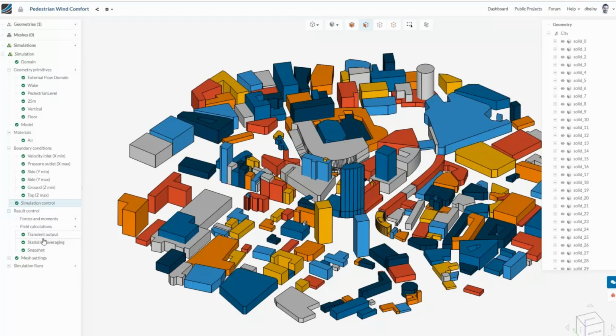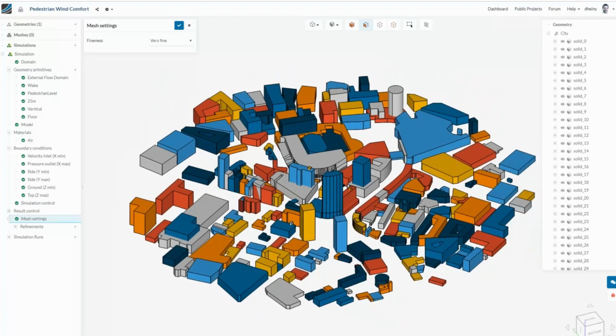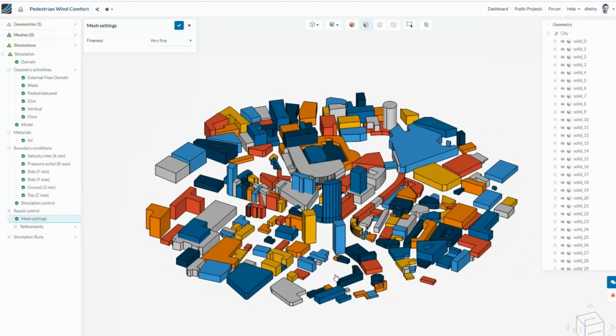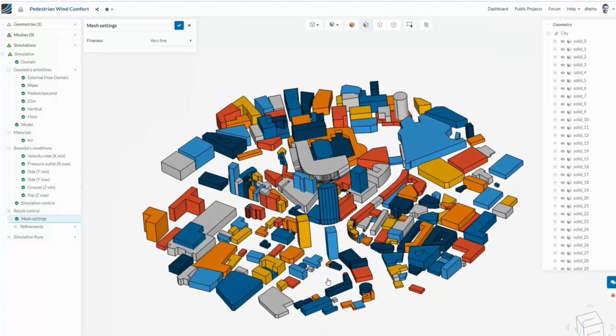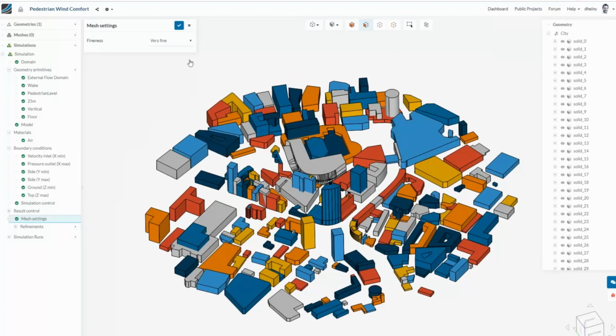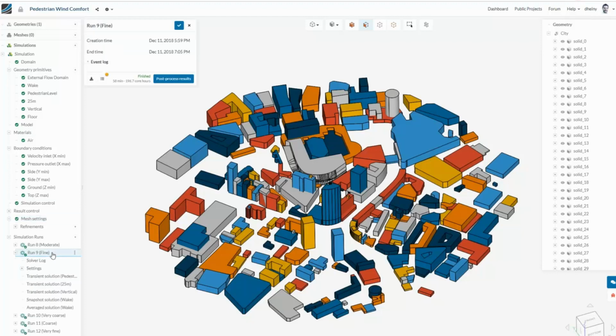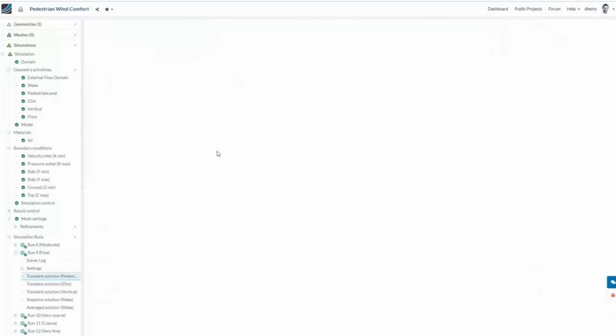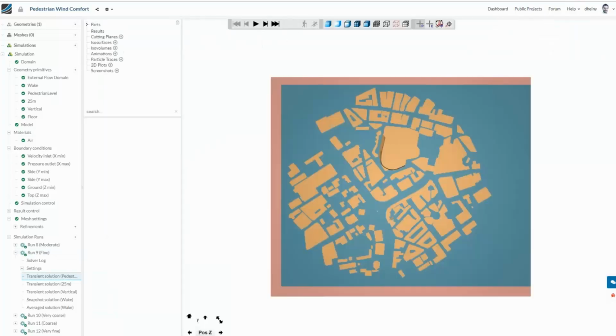Furthermore, anything else? The rest is maybe a bit very detailed. Then I can steer the lattice resolution. So again, we won't go into the details here, but I can drive the resolution of the mesh depending on which areas are of interest, which are not. I have the ability to locally refine on topology of the model, also driven by geometric primitives. Again, same story as with the other solvers in SimScale. And then I run it, right? Let's take a look. I'm going to show you later how you can drive fineness, etc. So I won't go into the details here, but I just want to show you this end-to-end.